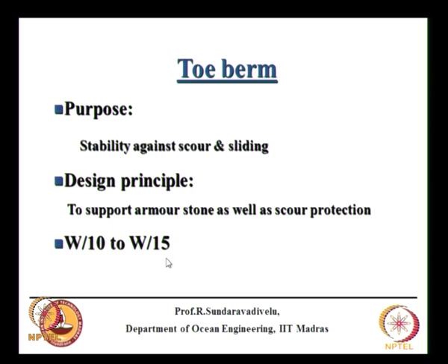Even armour layer there is some variation. If you have calculated armour layer is W, armour unit weight, you may not put W, you may put 0.75 to 1.25 times W, you may not put the single size stone, it is not possible.